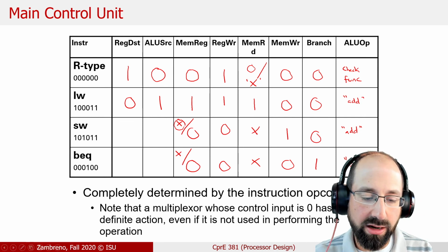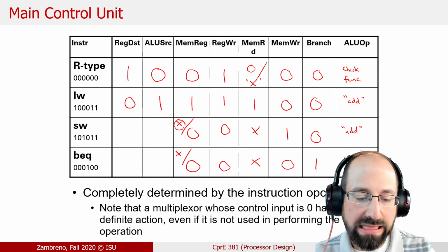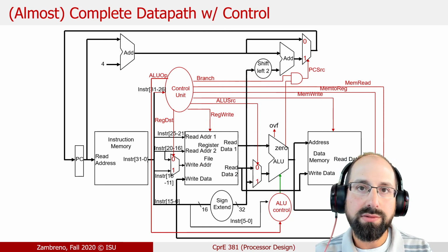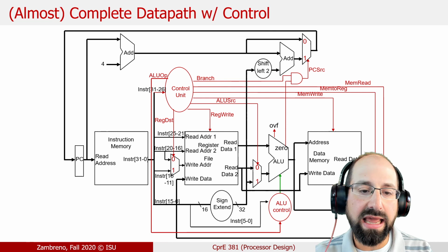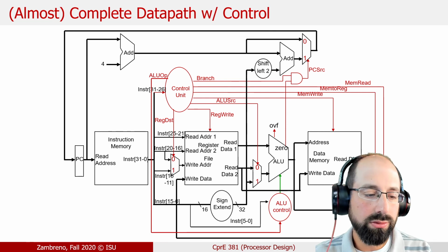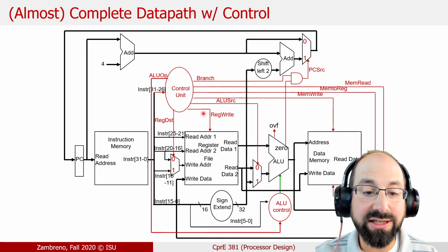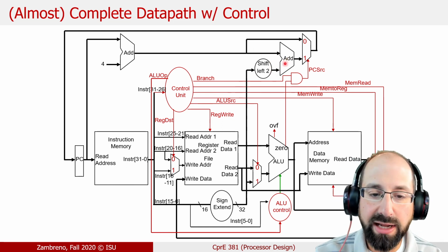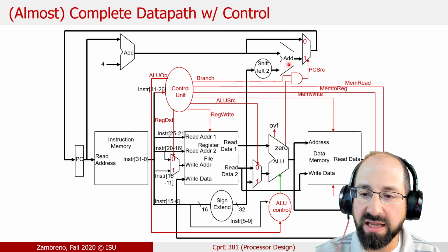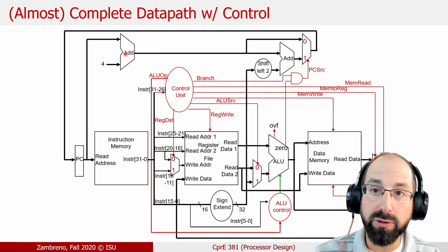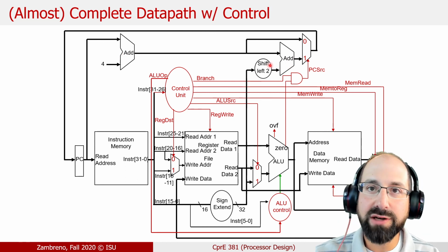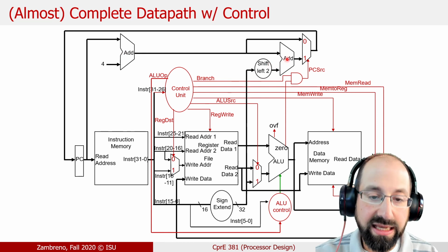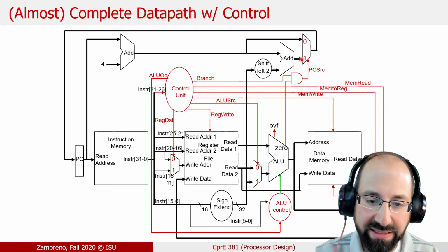And if we look back on our diagram for branch, that's exactly what's happening on this diagram here, right? We are confirming that two things are the case for us to actually take that branch. First off, there's all that somewhat convoluted looking logic for calculating the branch target offset. It's PC plus 4 already, plus the shift left logical of the immediate encoded offset to get our potential branch target new PC value.